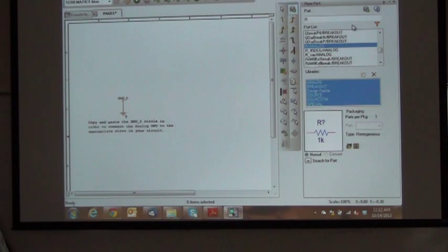We want the resistor. So in order to place the resistor, in order for it to snap to your cursor, you actually have to hit the part symbol again. See that? Then it gives you a part on your mouse and it follows you around. Now I'm going to place 3 of those resistors to make them look just like the one in the book on page 75. So click once, twice, 3 times. Now notice that I still have the resistor there.